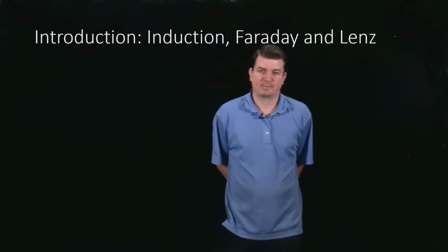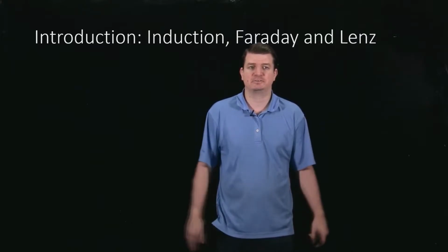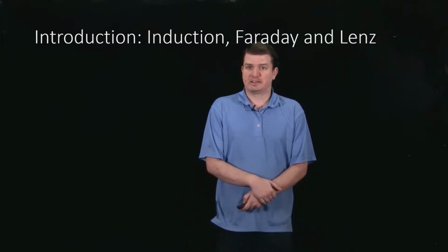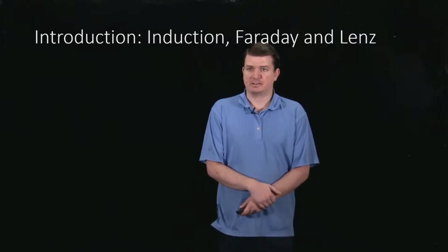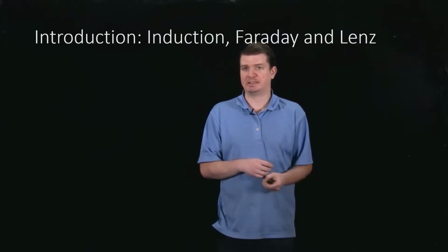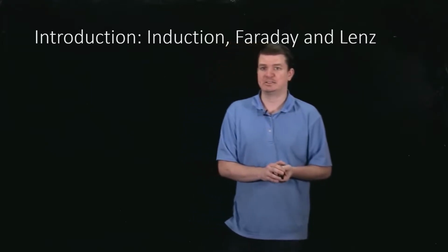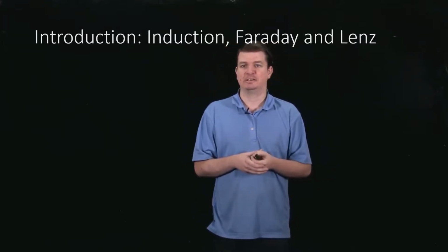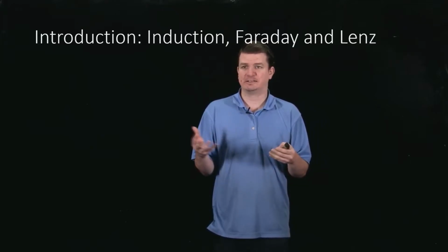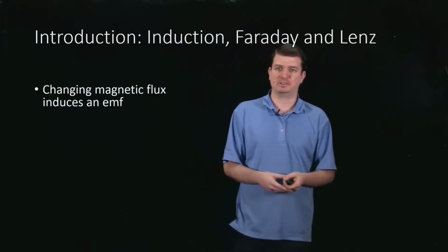So induction is a really fascinating phenomenon that basically amounts to understanding things about what's going on with flux. We introduced the concept of magnetic flux. That's just counting the magnetic field lines through some surface. It turns out that when you start changing the flux through a surface, that induces an EMF in that circuit. So if you've got a circuit loop sitting in a magnetic field and you crank up the magnetic field, or you decrease the magnetic field, or you change the orientation of the loop to change its area or its projected area in that field, all of a sudden you will find that it induces an EMF which results in a current through your circuit loop.